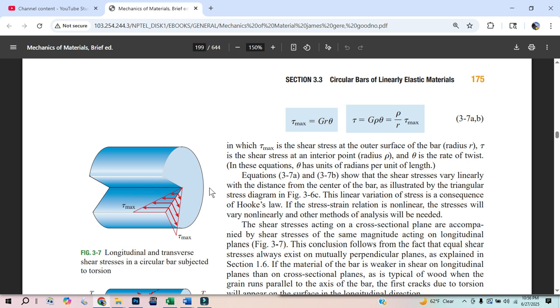When we twist on it and apply a torque, I'm essentially taking this ring of molecules and trying to twist it in a circle. And then I'm just going to envision the other disk of molecules is actually just welded to the wall. For this analogy, we could have a circular bar that's just two molecules in thickness. At some point we're going to have to take a differential slice of this thing anyway, so why not just make our cylinder, the shaft, the bar that we're torsioning, two disks of molecules in thickness,